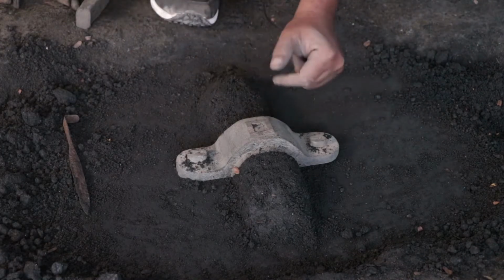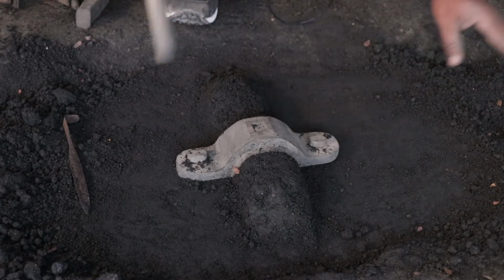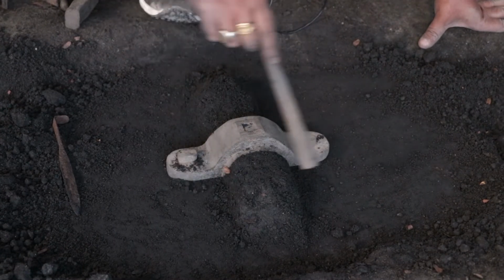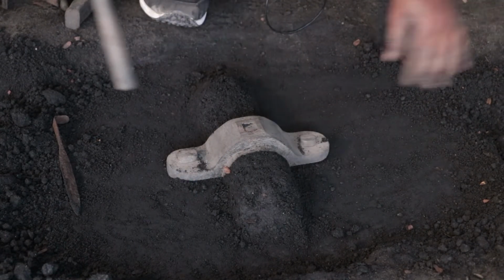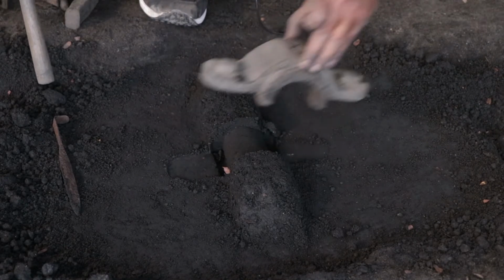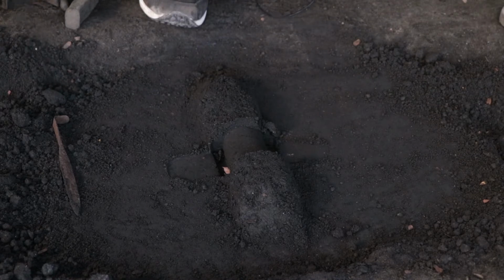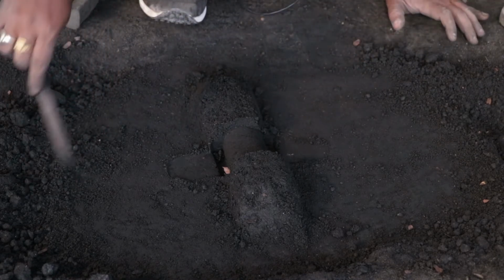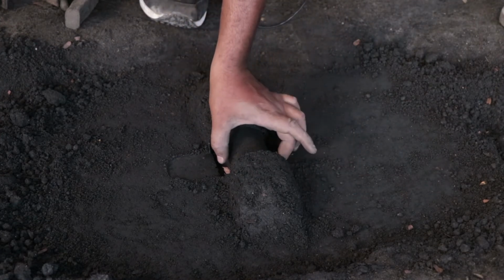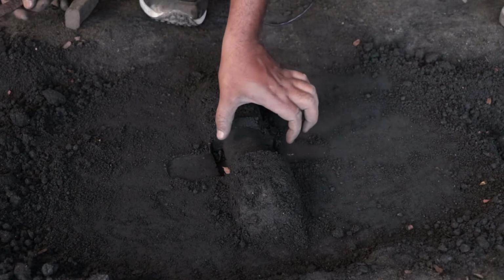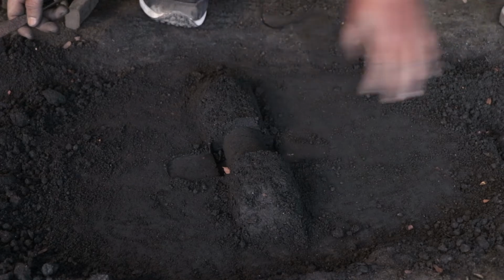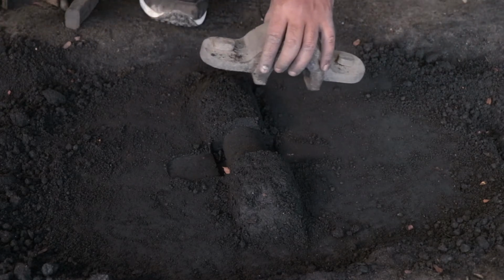Now, with the help of any wood piece, just tap this pattern and pull it out. After completing this, you can see that three parts have come out: one, two and three. The center part is a bit plain and it is of a smaller size. We need to make it long and parallel like this so that it can fit easily and we can complete the rest of the operation.